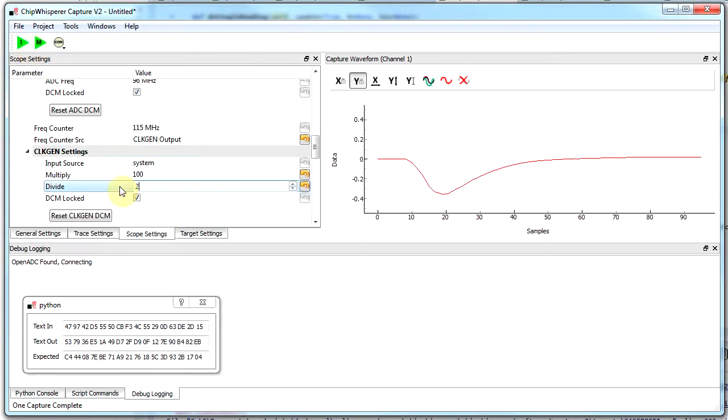And you can keep increasing the frequency here, go up to 150 megahertz, and we will start to see, actually here it's working pretty well. So there may be points that it works, points that it doesn't work. And you can sort of confirm based on the length of this side channel analysis trace that you are in fact using the expected frequency.